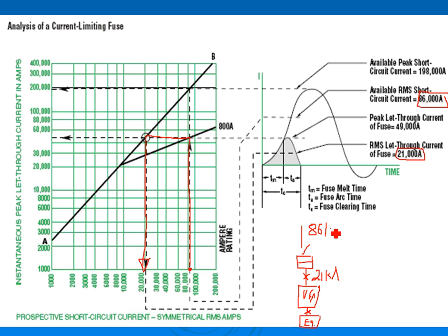86K. Who cares? Your chances of surviving for your equipment improve. You limited two things: you limited the survivability of your equipment, the VFDs, the soft starts, the starters, and you also hugely reduce the arc flash that's coming out of this system. Because the arc flash, guys, is a function of time. So you hugely reduce the arc flash. Okay, so that's the heat, that's the cooking.